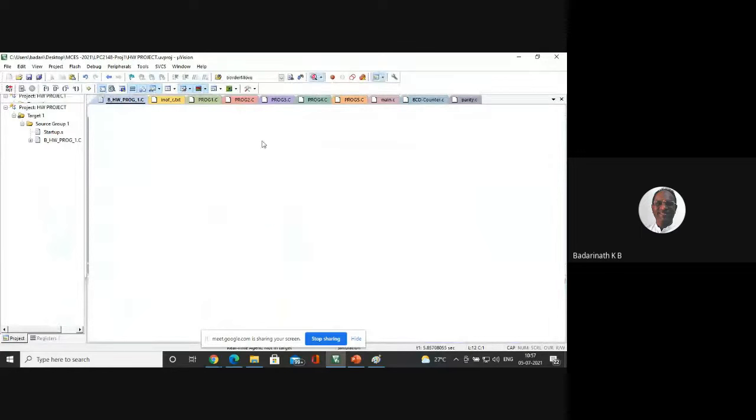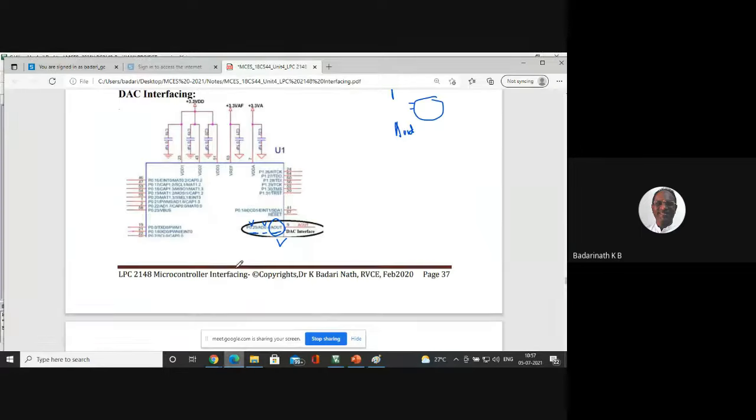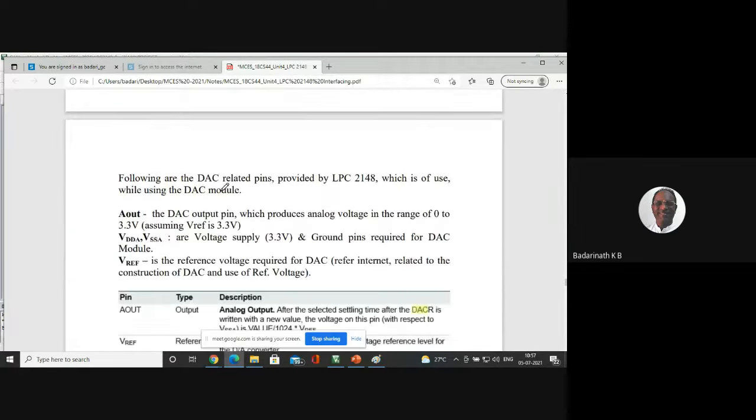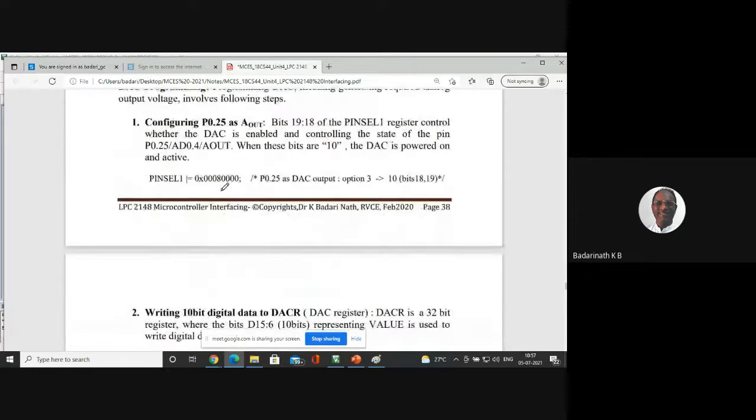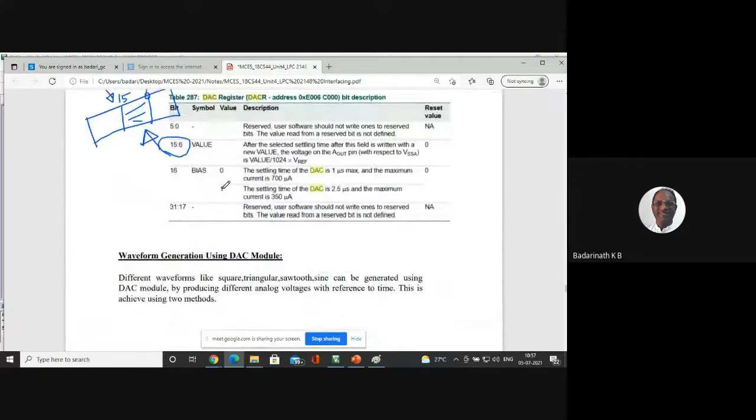Now we will go to a very important concept in waveform generation, the concept called lookup tables. Whenever you want to generate waveforms, there are always two types of possibilities. One is using the program to compute the analog voltage at runtime. That is what we did now.